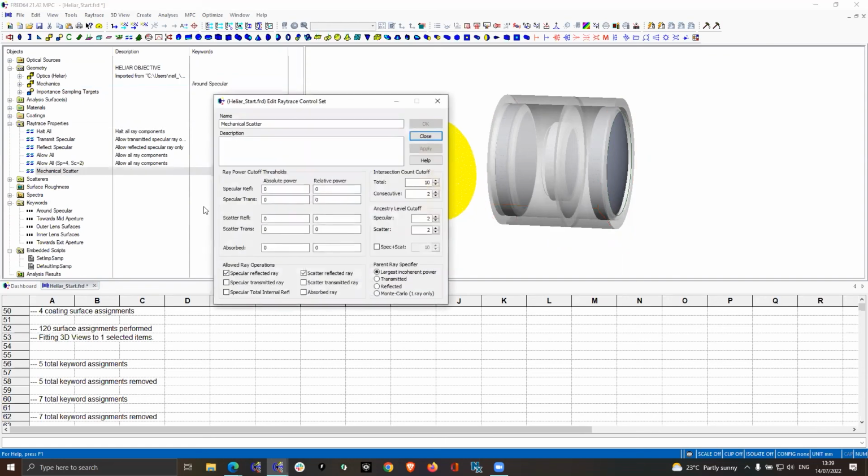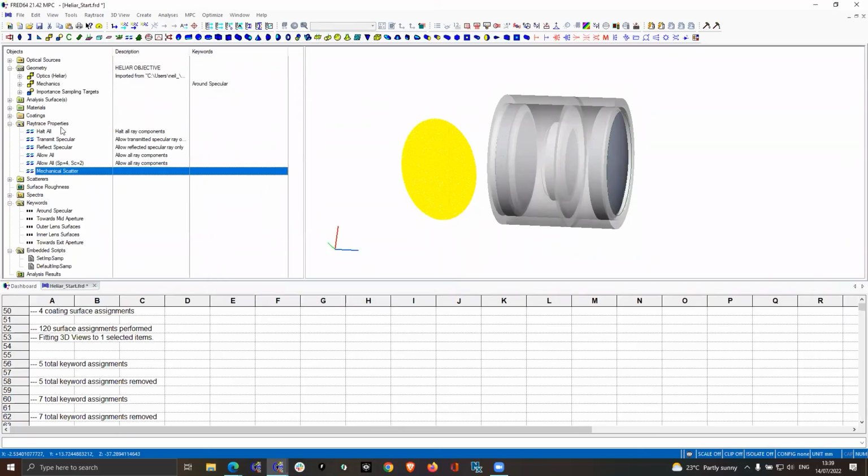And it's the coatings that tell us how much power that ray has. So in this very simple demo here, we said we had 100% reflective coating, which essentially means that the specular ray has all the power that it should have after the energy for scattering has been taken out, but there's no further absorption. Hopefully that answers that question.